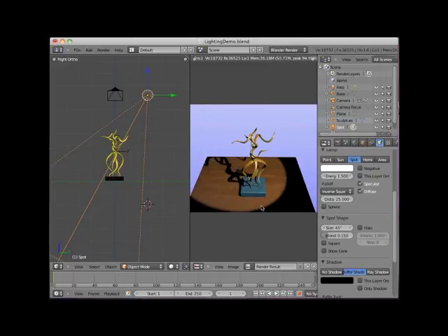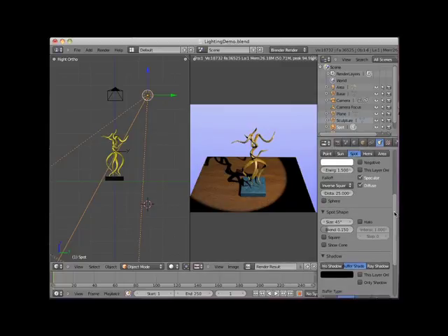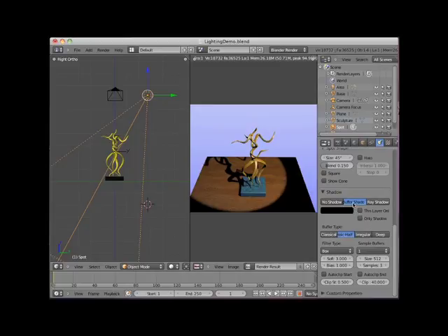Here we can clearly see the shadows cast by the sculpture. By default, the spotlight has its shadow casting properties activated. It is possible to turn these off by clicking on the No Shadow button. The default shadow producing mechanism for the spotlight is buffer shadows. The spotlight is the only Blender lamp object that presents this buffer shadow option. The point, sun, and area lamps are limited to ray traced shadows only.